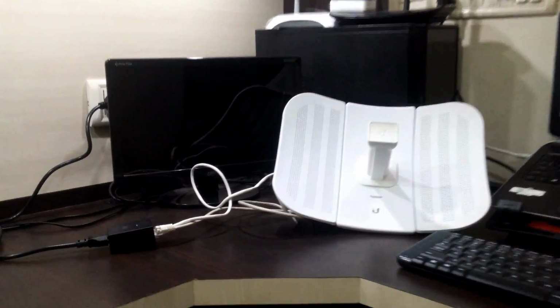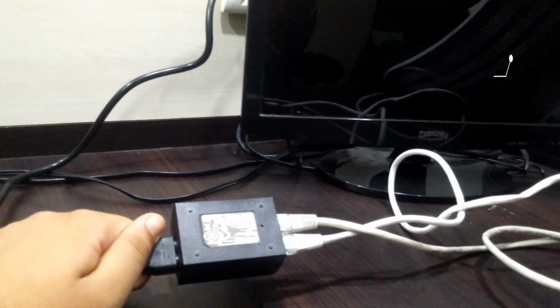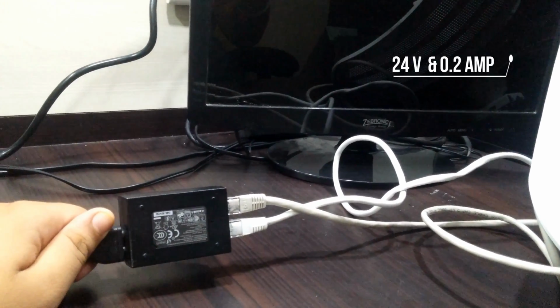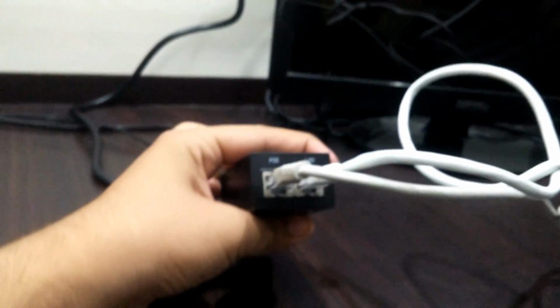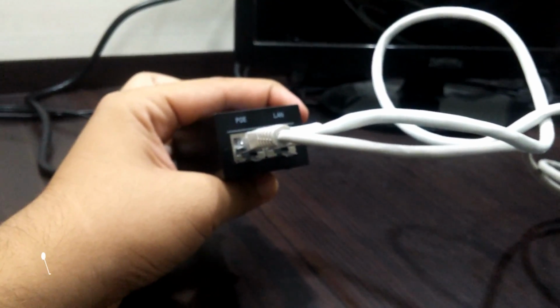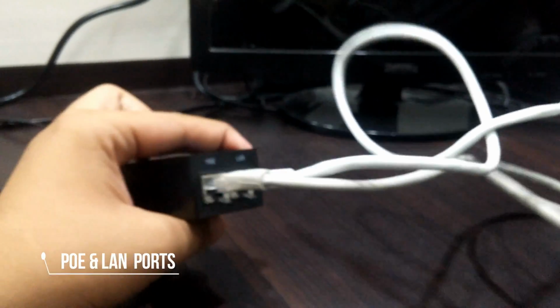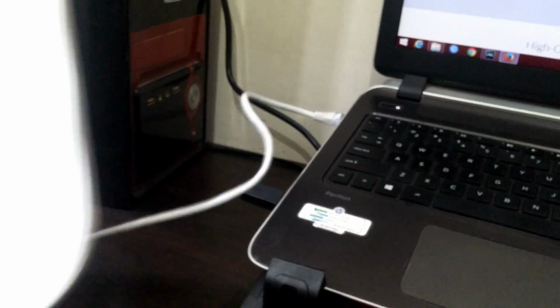In this, we connect our Litebeam with a power adapter given in our package, of 24 volts and 0.2 ampere. In this power adapter, we have two cables, one is the PoE cable and the other is the LAN cable. The PoE cable, that is this one, is connected to our Litebeam, and the LAN cable is connected to our laptop.